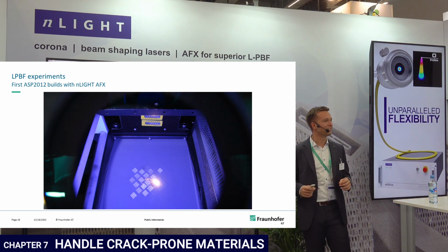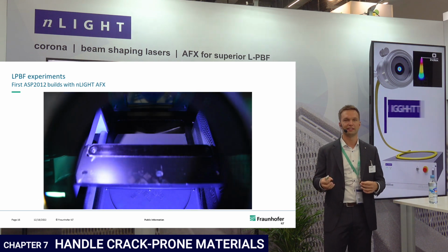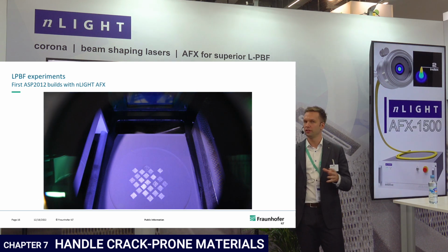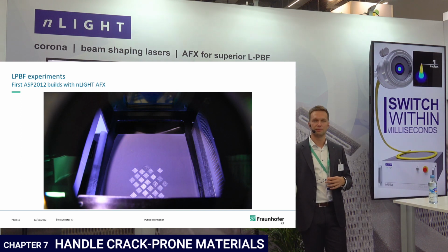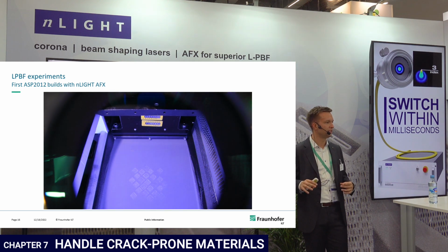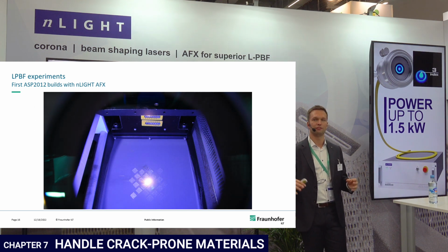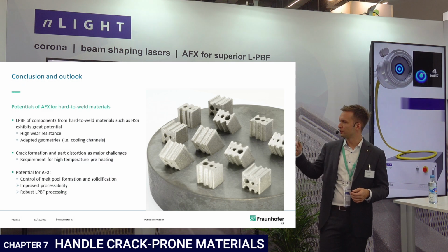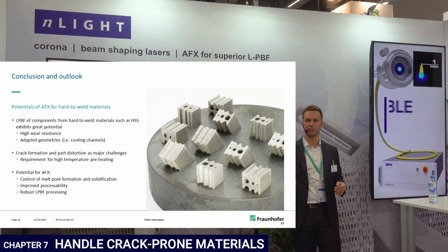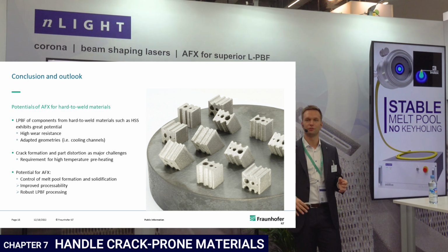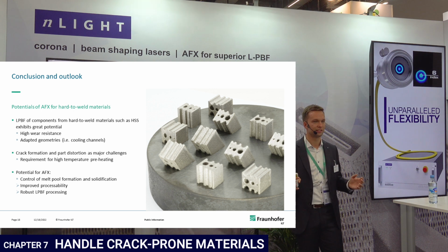It's a really nice process. First impression is the process works fine. We will do in-detail analysis, melt pool geometry versus crack formation, and we really see a lot of potential when it comes to processing of these hard-to-weld materials that are very sensitive when it comes to the temperature fields and the continuous remelting. And the potential for AFX is obviously that we have additional degrees of freedom apart from preheating to very high temperatures or modifying just our laser power, scan speed and hatch distance accordingly.